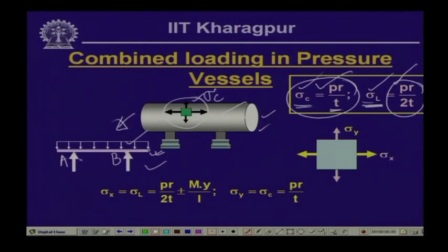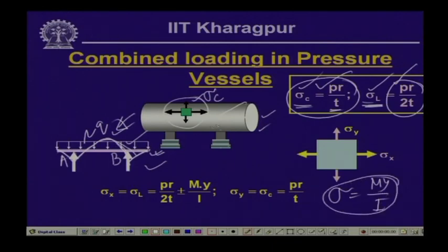Now, as you know, when this beam member is subjected to a uniformly distributed load of Q, we will get a moment diagram which will look like this. Because of this bending, there will be bending stresses, and as you know, the bending stress introduces the normal stress, M y by I, and depending on the position of the element, it could be compressive or tensile with reference to the neutral axis. So, that will contribute to the normal stress.